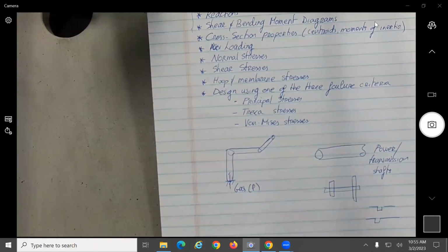And what's going to happen once the gears start moving? What happens is that the load is not static anymore, but it becomes cyclic, no? So we're going to have to consider a new failure criteria. That will be the Goodman method.